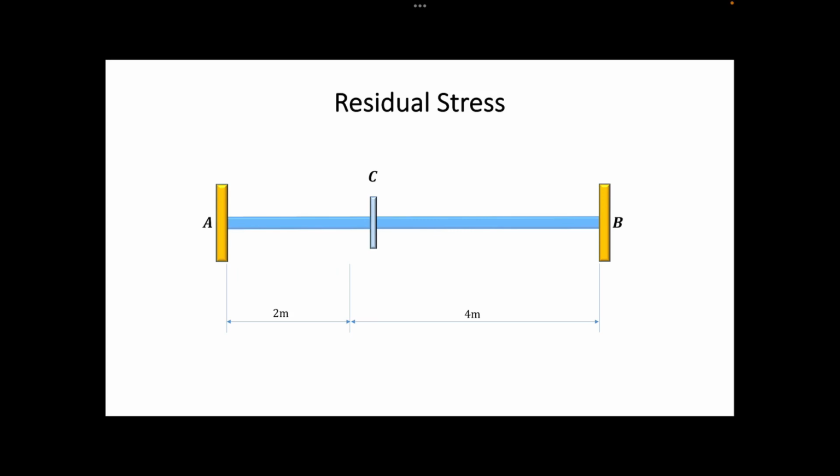As you can see, due to the plastic permanent deformation of segment AC, the bar does not go back to its original shape. Because the permanent length of the bar is now longer than the original length, there can be compressive stress remaining in the bar. As such stress remains in the bar when its original cause, the external load P, has been removed, it is called residual stress.